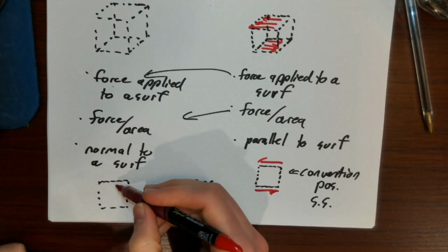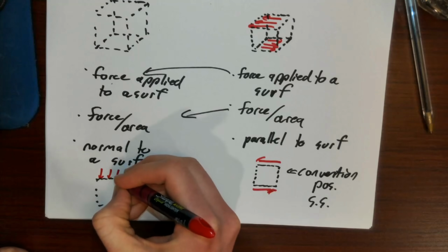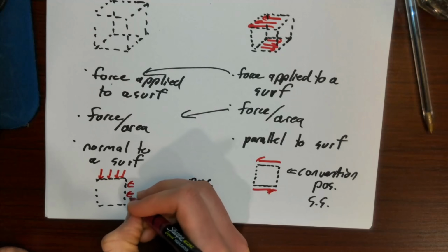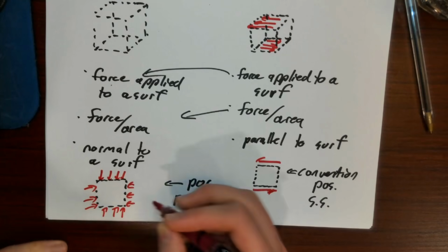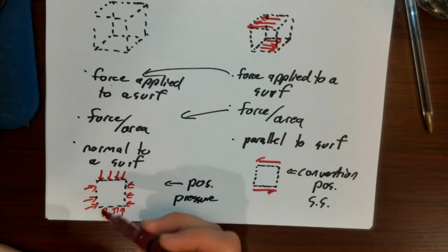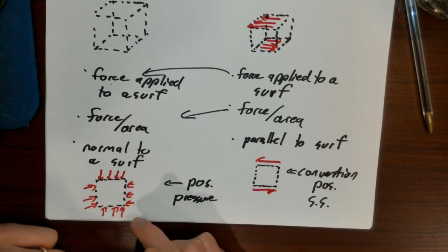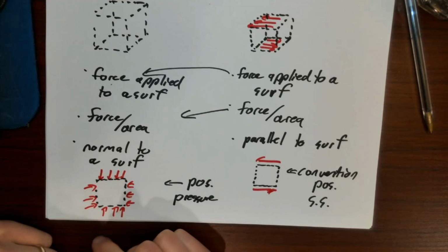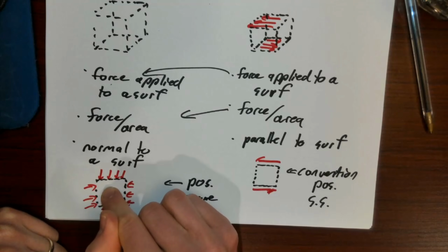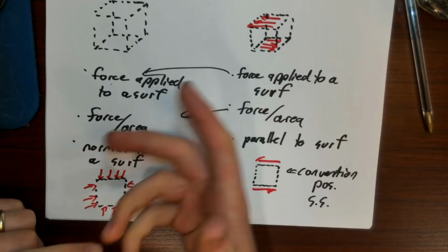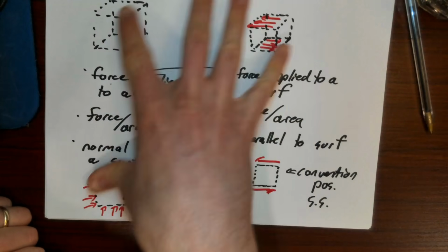So if I'm thinking about, hey, what is pressure doing to this chunk of fluid? Pressure is acting inward. So if pressure is positive, then pressure is acting inward on this chunk of fluid. And it is possible to have pressures that pull on things. It would just be negative in that sense, right? So if I'm defining by convention pressure acting inward, and in physical reality pressure is pulling outward on something, then the pressure will just have a negative value, right? So this is the convention.